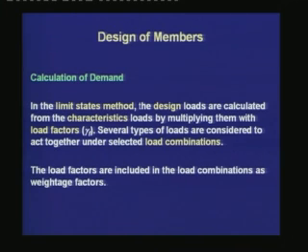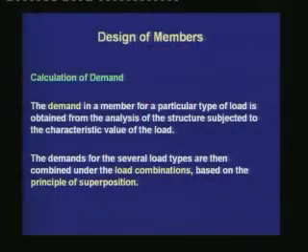The load factors are included in the load combinations as weightage factors. The demand in a member for a particular type of load is obtained from the analysis of the structure subjected to the characteristic value of the load. The demands for the several load types are then combined under the load combinations based on the principle of superposition.